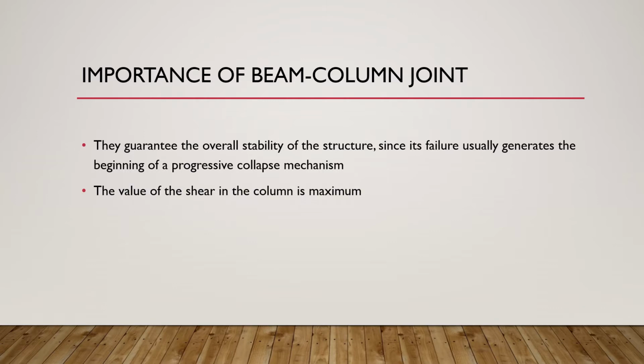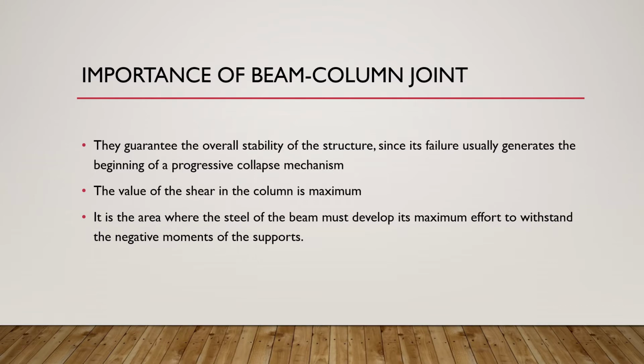The value of the shear in the column is maximum. This can be seen in the diagrams when we design the columns. It is the area where the steel of the beam must develop its maximum effort to withstand the negative moments of the support. There is also bond deterioration of the longitudinal reinforcement in cyclic loads, like earthquakes, and they present an inversion of moments during earthquakes.